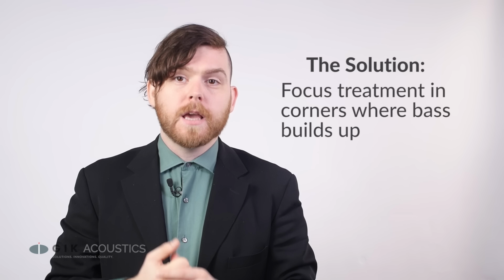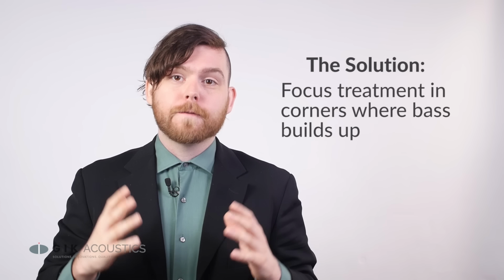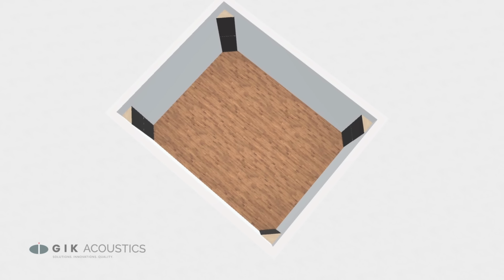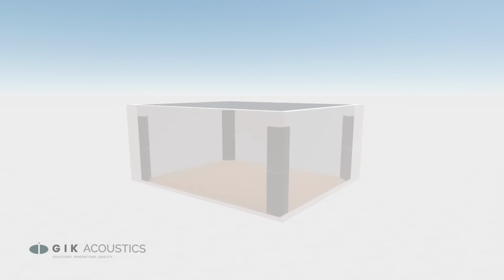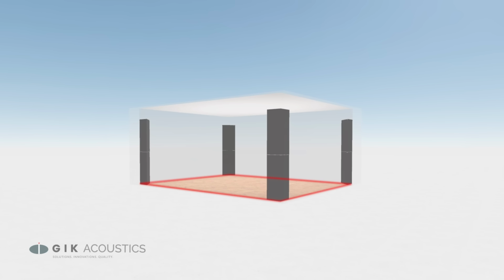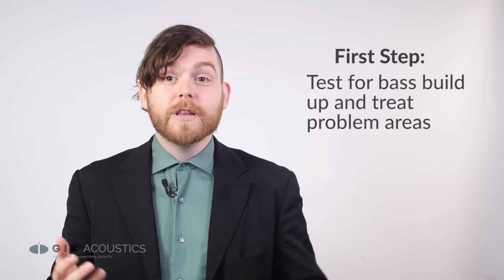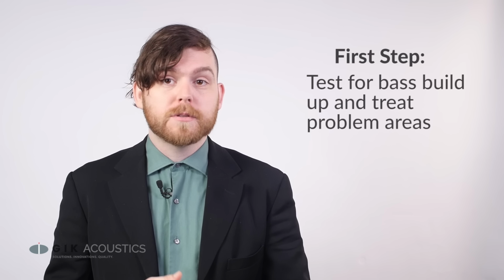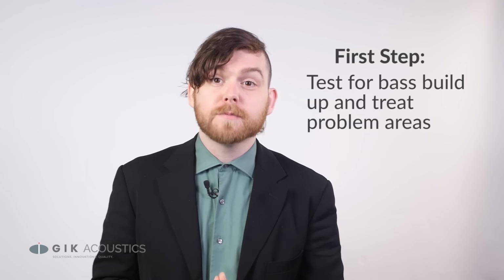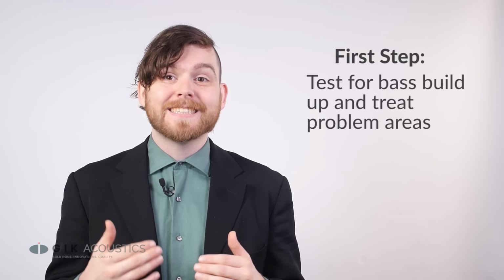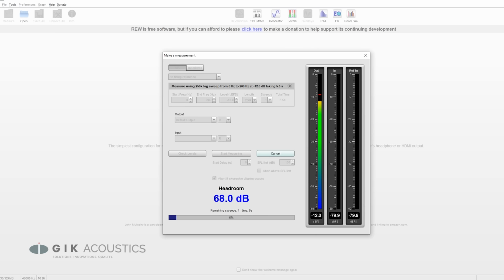It's common to see bass traps stacked floor to ceiling in the vertical corners of a room, but there are actually 8 more corners that can benefit from bass trapping. The corners along your floor and ceiling that run along the perimeter of your room also cause bass buildup issues and can benefit from treatment. Treating all of these corners isn't always feasible depending on your budget and space limitations, but luckily there's a few ways we can test to see where we should localize our treatment.